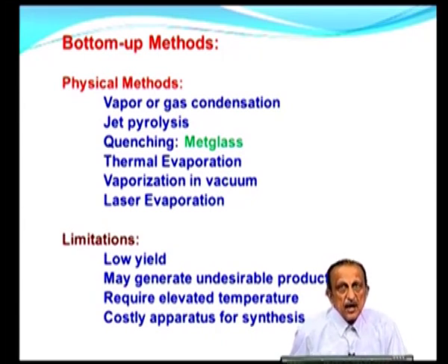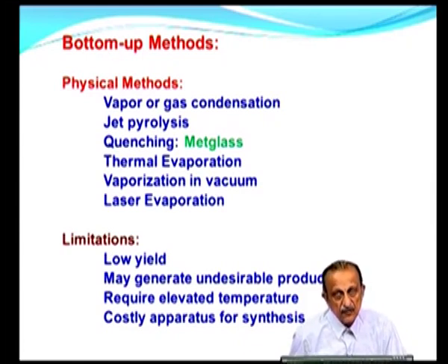If the array is very large, let us say you are talking about a crystal of the order of a centimeter in size, containing Avogadro number of atoms, then as the assembly process proceeds, as the atoms come together to form such a macroscopic crystal, the chances of defect formation, such as dislocations, that is atoms in the wrong place, wrong crystallographic phase, are increased when the total number of atoms that are assembled together is increased.